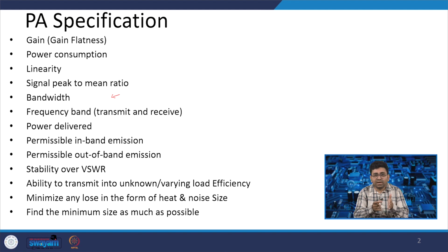Stability over the voltage standing wave ratio. So, stability is also an important parameter for the power amplifier, because if it goes to instability, then there is a possibility that the device or circuit that we are using might burn, because very high power is involved.